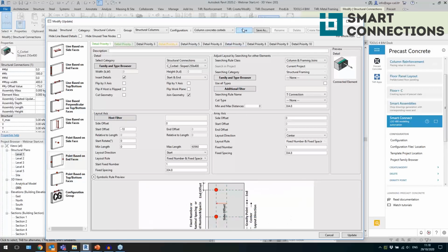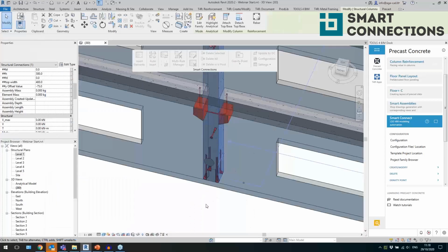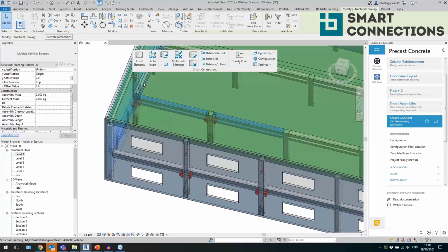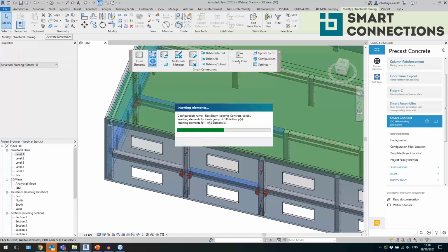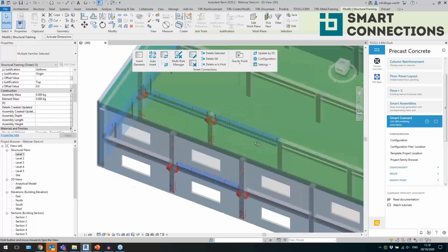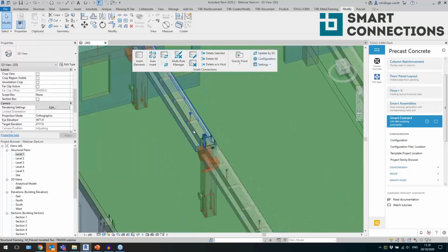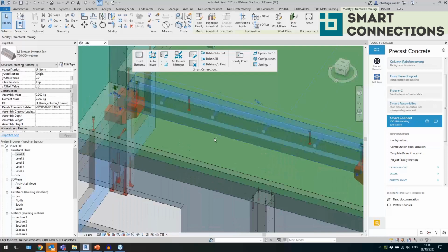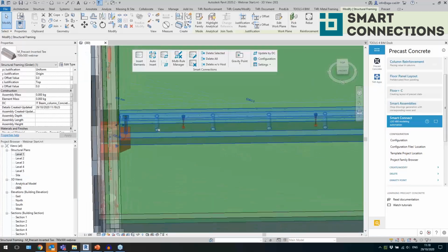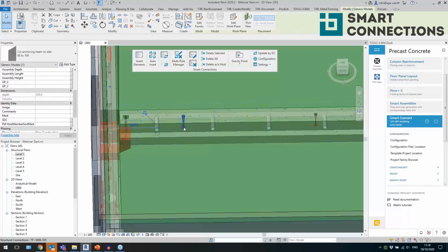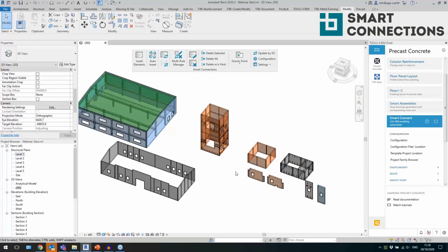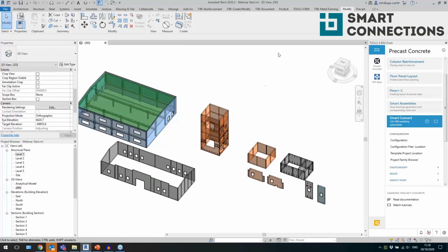You can save that configuration to your computer, so it helps you to get started, right? A couple of beams, let's do that as well. Okay, and I'm just gonna auto insert. Auto insert means that I can add the name of the configuration, which should be used for your elements, into the properties, and then it will know what to do later on, right? So I placed just some avoid families, some lifting families, and so on. Okay, so that's enough about smart connections, I guess.